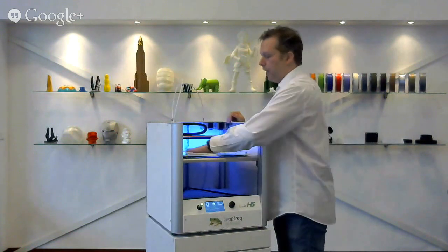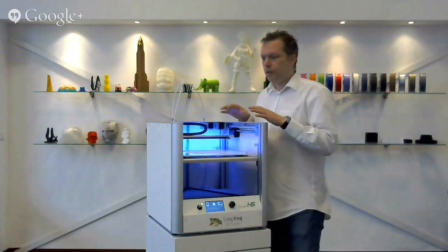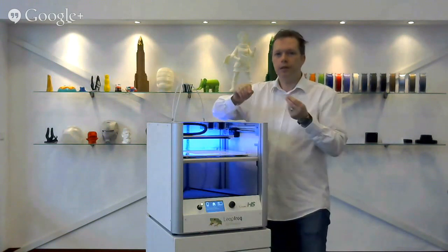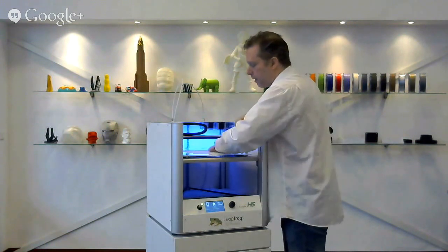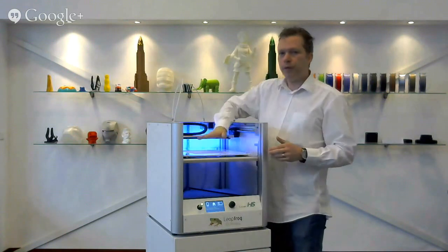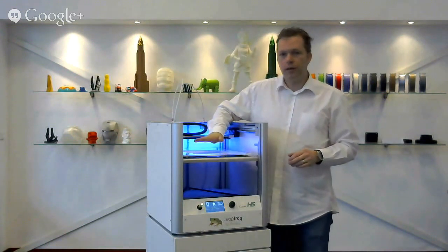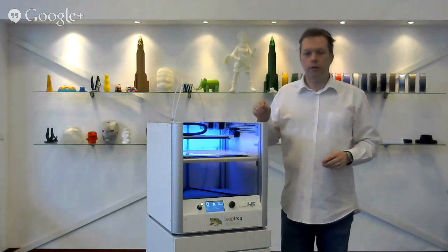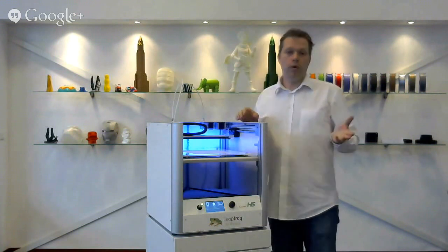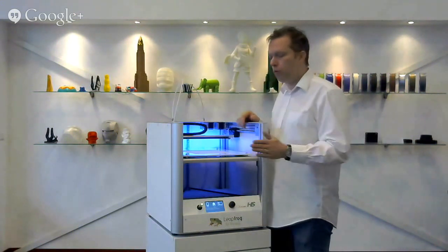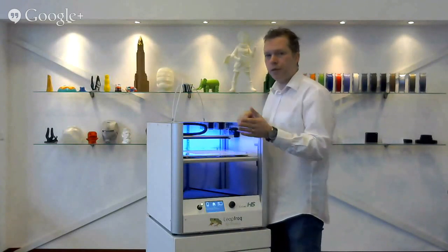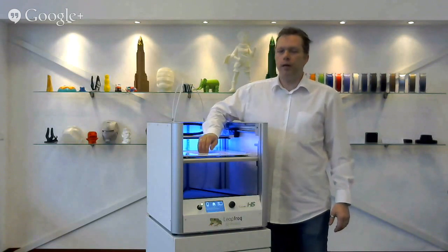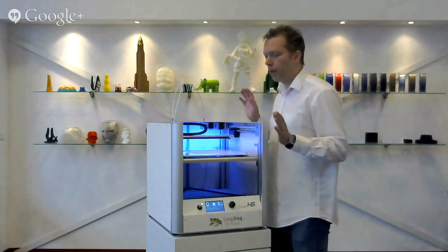So once your sticker is placed, sometimes the material still won't stick to the sticker because you have grease on your fingers. The small grease from just wiping the sticker down and pushing it down, the grease from your fingers will get on the sticker. And that way the filament won't stick to it because it's greasy. If you have simple alcohol wipes, they're really cheap. Use an alcohol wipe and briefly just wipe it. If you wipe it really hard, you will remove the top layer. So make sure you just wipe it like that and it's done.